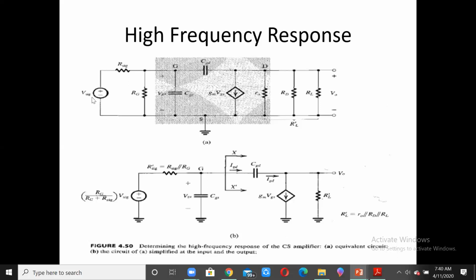So that means Vsig multiplied by Rg divided by Rg plus Rsig is the value which we have over here, or you can consider it something like this. The current flowing through this is Vsig divided by Rsig plus Rg, and that current multiplied by Rg will give me the voltage across Rg, that is the Thevenin's equivalent voltage, and that is what is being mentioned over here. The rest of the thing over here is as it is,